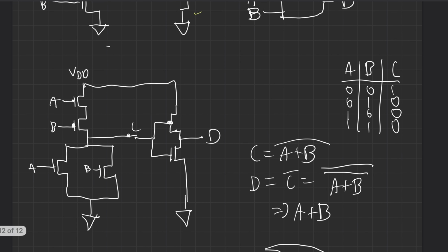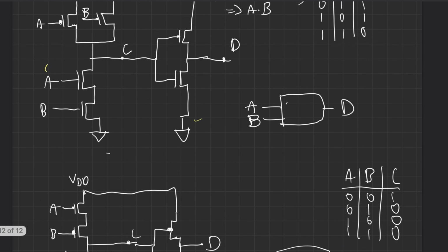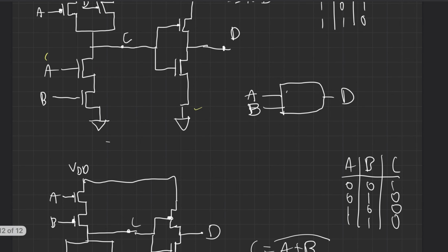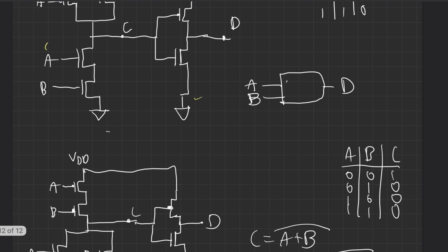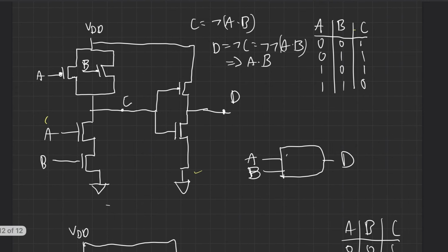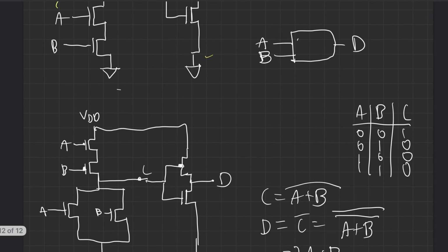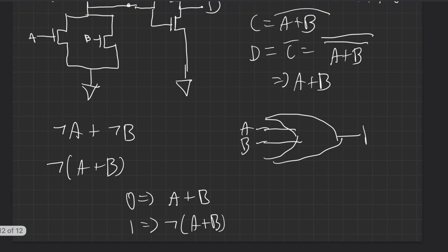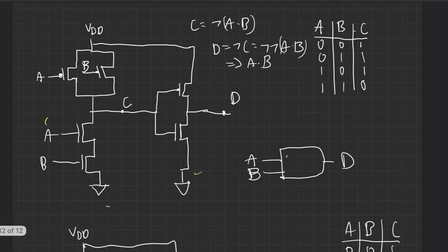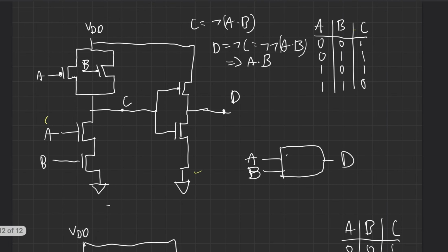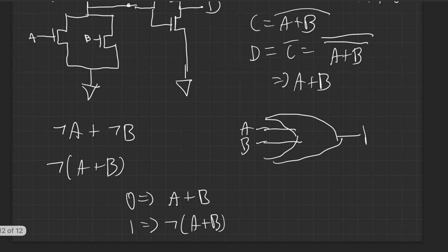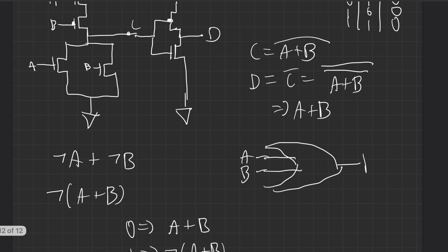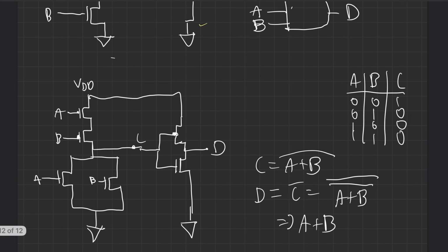So you can do the same thing here. Because this is in series here, we could say we're looking for a not A and B, which is actually what this is. We'll talk more about De Morgan's theorem, but that's kind of a preview. Unfortunately, a lot of these concepts are related, so I'm just showing you early. Not that you need to know this right now. But it's kind of cool. You can analyze any arbitrary circuit.